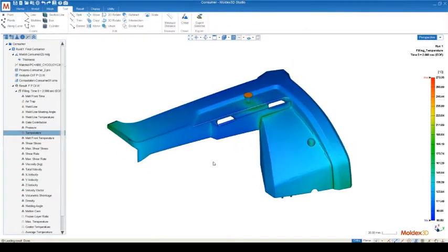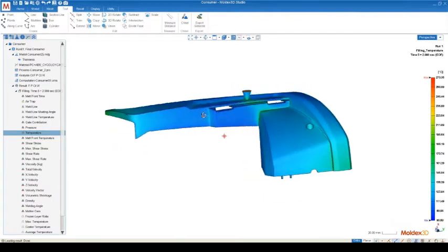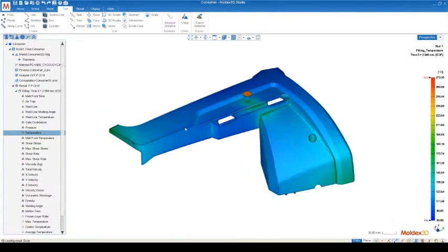Shear heating is going to be a consequence of how fast I'm moving my material. So the amount of friction that occurs from my melt or from my viscous flow to my stationary mold plate or my stationary mold base, that's what's going to cause the temperature to increase over the duration of flow. Now, there's two competing effects going on here.